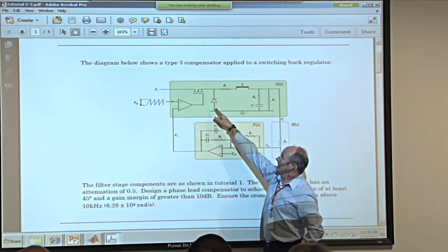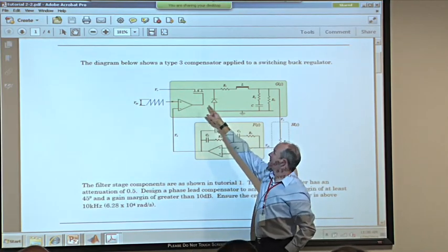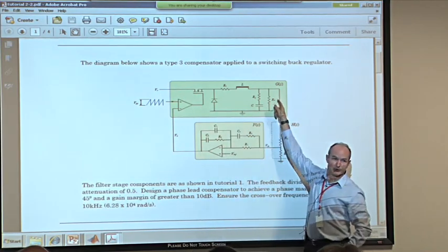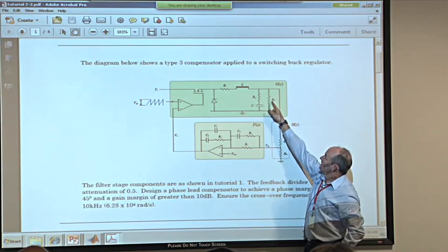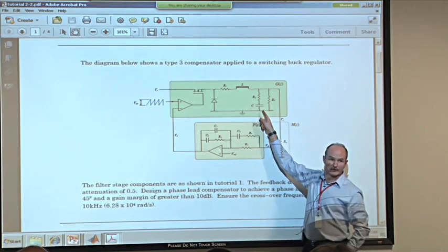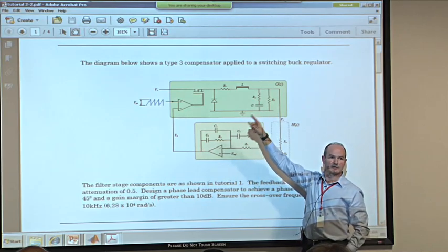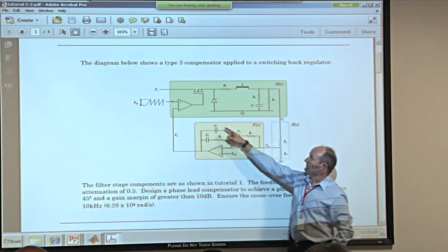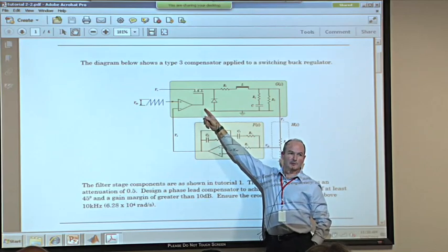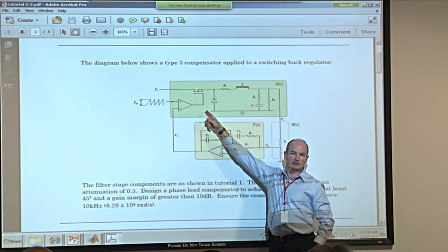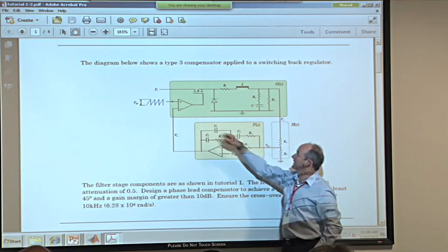It's chopped up by a pulse width modulated signal through this MOSFET. So the output is a smoothed, chopped signal, smoothed by this inductor and capacitor network. So the output voltage is always less than the input voltage, and the two are related through the duty cycle of the PWM that's chopping up the input. Basically, that's the operation of the buck.